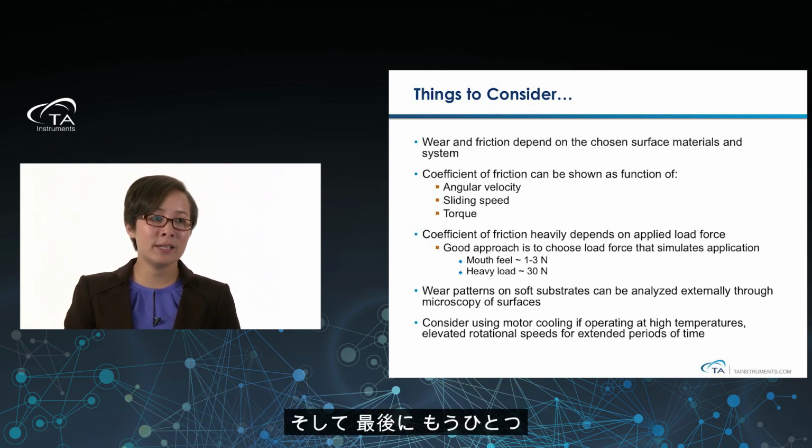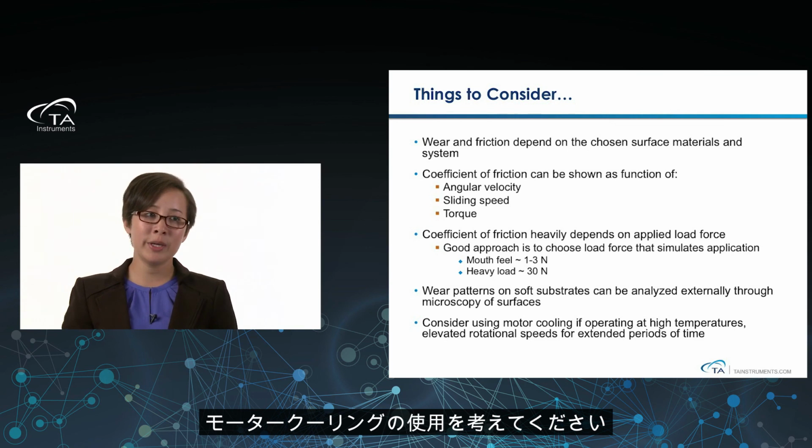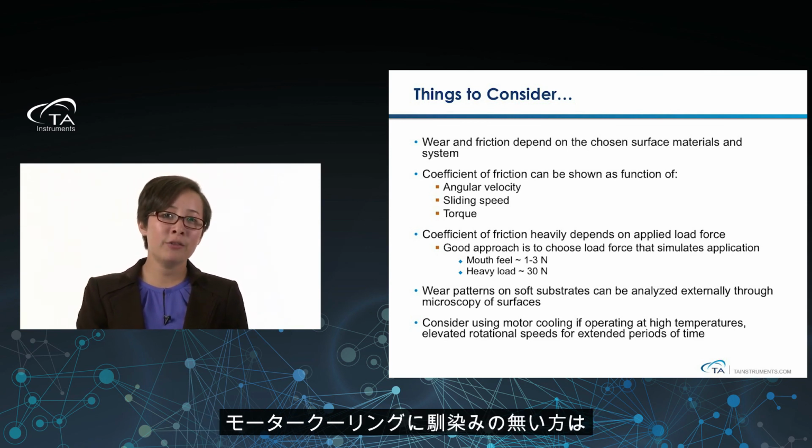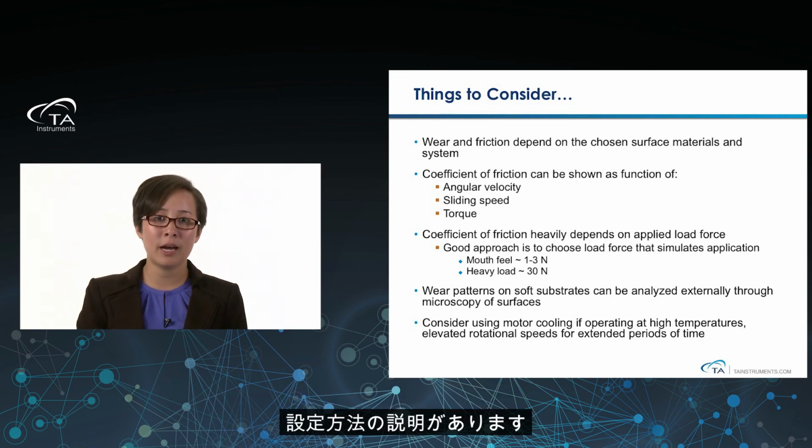And then one last thing is if we are operating at very high temperatures at these really high rotational speeds for a long period of time, then we can consider using motor cooling. And if you're not familiar with motor cooling, just check out our Trios online help. It will tell you how to set everything up.